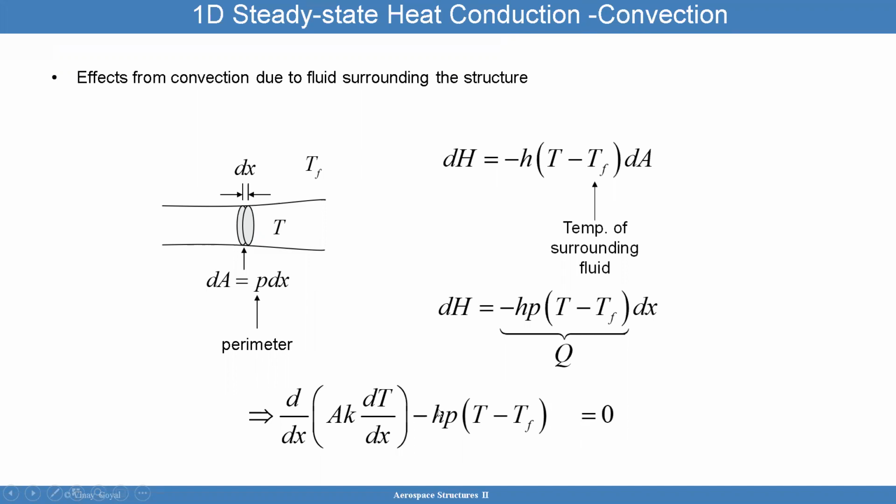h is a material property, or almost like a way of calculating how this h could impact. So the greater h is, the more the transfer of heat out or in from the fluid into the material. For example, if I put a coffee cup in a convection oven and there's no air moving, it should take longer for the cup of coffee to warm up compared to a situation where the convection oven is blowing hot air at very high speeds into the part.